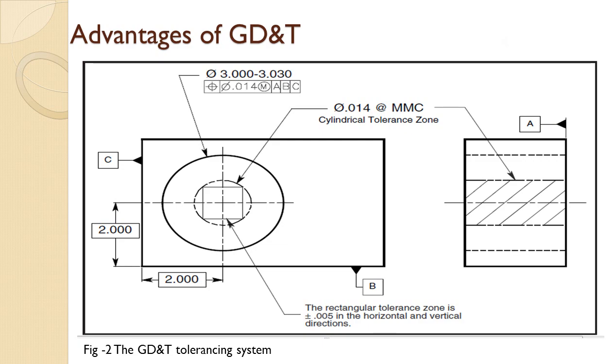a rectangular tolerance zone. In this figure, the tolerance zone is oriented perpendicular to datum plane A and located with basic dimensions to datum planes B and C. Basic dimensions have no tolerance directly associated with the dimension, thus eliminating undesirable tolerance stackup. The full length of the axis through the feature is easily controlled because the cylindrical tolerance zone extends through the entire length of the feature. Unlike the rectangular tolerance zone, the cylindrical tolerance zone defines a uniform distance from true position.